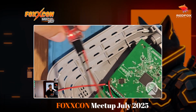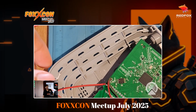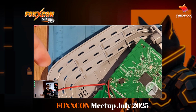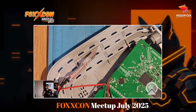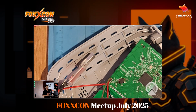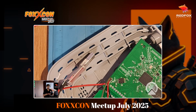All right. Now, as you can see, there's already a red light going on here, and you may also have a question about why we connect ground if we're not connecting VCC, because if voltage is already present on the device, why do we have to provide ground? The simple answer is that ground needs to be common for both devices, otherwise there will be a lot of noise. The disturbance is caused because not all grounds have the same resistance. If resistance is different, then current conductivity will also be different, which will cause a lot of data integrity issues and a lot of jargon to show up on your console out here.